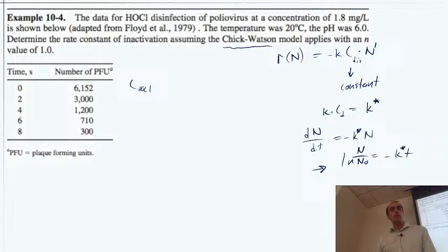It turns out the pKa, again, we'll give you that reminder of what all that means if you don't remember, is about 7.5 for free chlorine, and therefore at pH 6, we're an order and a half magnitude away from that. So we're probably expecting 98% or so of the chlorine to be in the HOCl form. So this would be something like 98% of total chlorine.